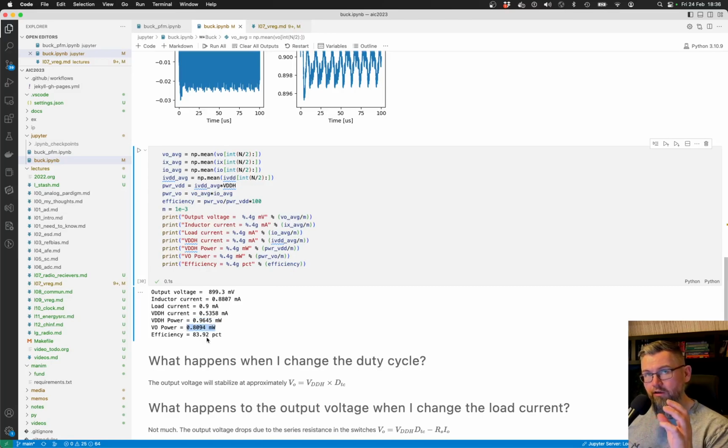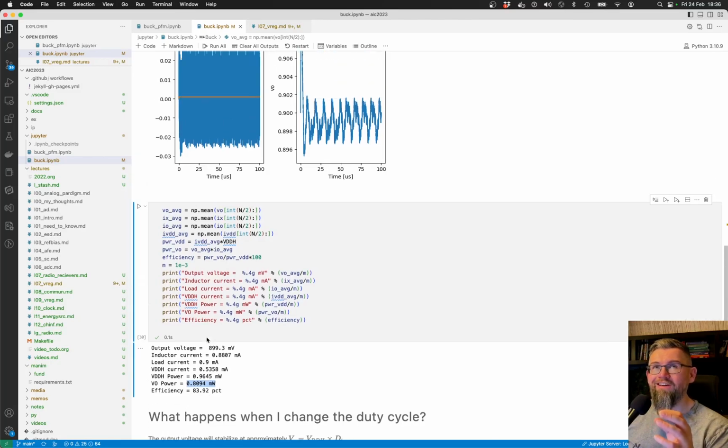So there's a power conversion and not a current or a voltage conversion. Now it's possible to make DC-DC converters with maybe 90+% efficiency, and that's why we use them. We can convert power, so voltage times current, on the battery into voltage times current on a low voltage. They're much more efficient. They use our electrons more efficiently.